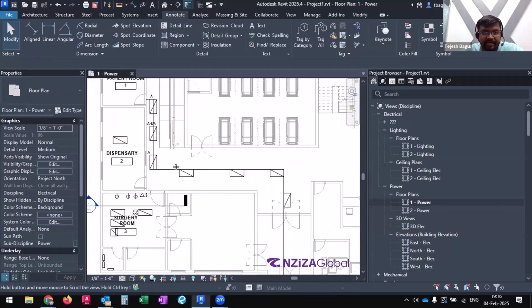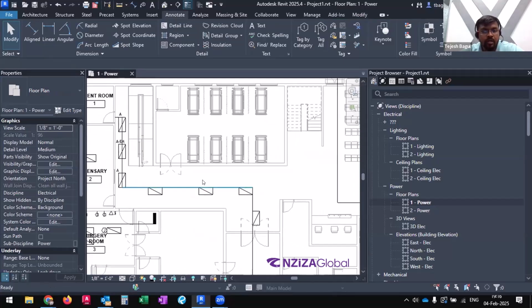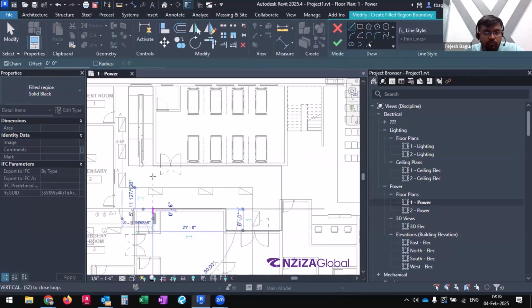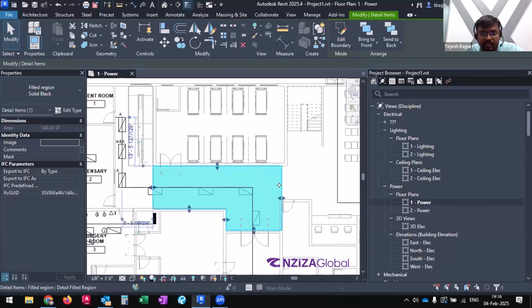Just like we had taken the cut for this area of the corridor, we can have another cut over here that will take care of this part of the corridor. One more point to note: for this given area, if we get the option of being fine with just one emergency light fixture, make sure there are no blind spots.